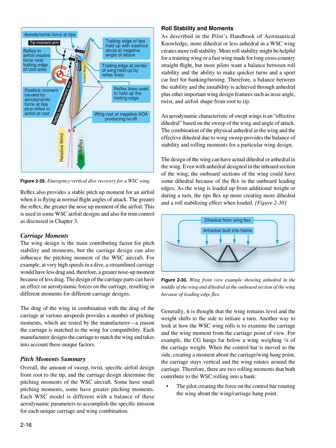Carriage moments. The wing design is the main contributing factor for pitch stability and moments, but the carriage design can also influence the pitching moment of the WSC aircraft. For example, at very high speeds in a dive, a streamlined carriage would have less drag and, therefore, a greater nose-up moment because of less drag.